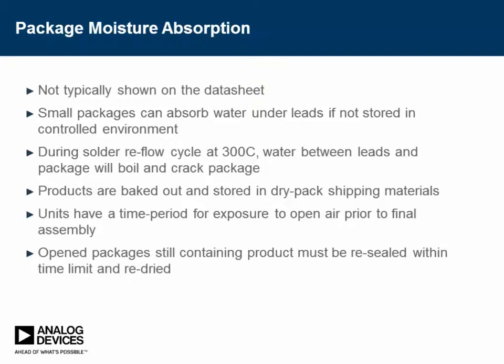But even though these things are made very carefully, there can be small voids that can absorb water under the leads if they're not stored carefully. And that water, during the reflow cycle at 300 C, will boil and crack the package. Now, you find it right away, but it sure is a pain to have it happen during assembly. What we do is bake the products out and put them in a dry pack material, or a shipping dry bag, so that they're okay when they're shipped and they're usable.